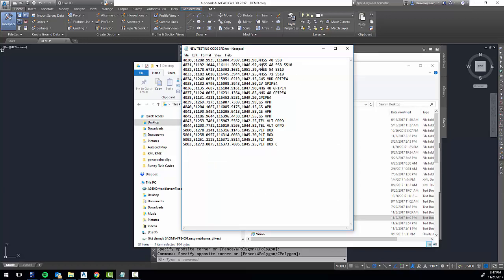All right, this is book 3. Basically, what we're looking at here is a manhole, sanitary sewer. Then we're going to tell it what size that manhole is. It's 48 inches. And then we're also going to tell it what kind of line work is coming out of that. So we're telling it it's a sanitary 8-inch main coming out of there. So as we go to the next one, it's 48 inches. Now we're going sanitary 8-inch, and then we're pulling out of that thing at sanitary 10-inch.